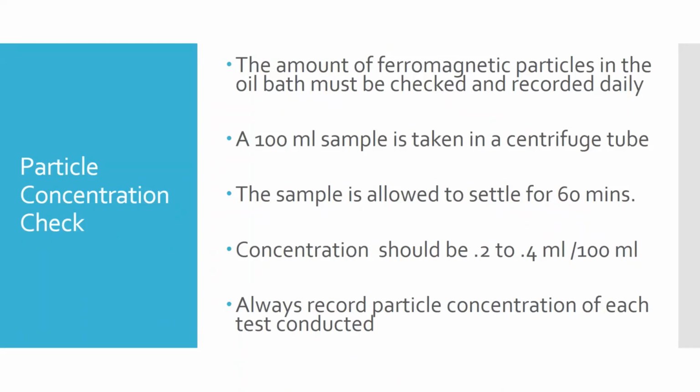If you're in a lab doing this, you have to do it. When we're doing this in lab here, you don't necessarily have to wait an hour before you start doing your tests. In fact, if that amount comes out low or high, you don't have to redo your test. But if you were in a lab where you were certifying parts, if that concentration came in low or high, you would have to redo any test done at that incorrect concentration. Okay. Over time, that concentration will go down as particles are pulled out as parts are cleaned. And we can add a little bit more of the powder to it and mix it up.